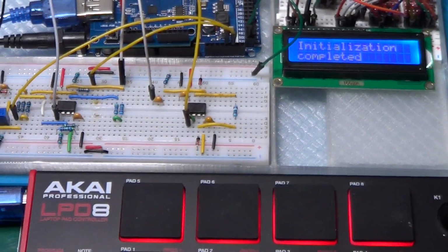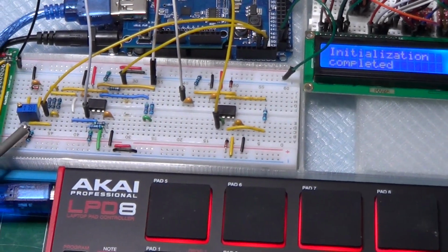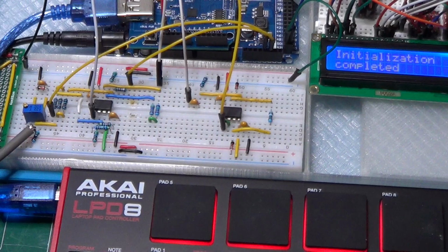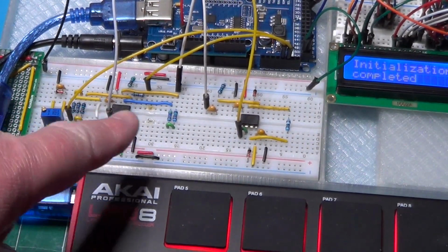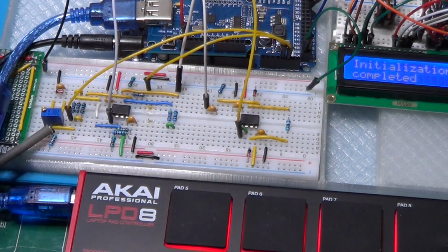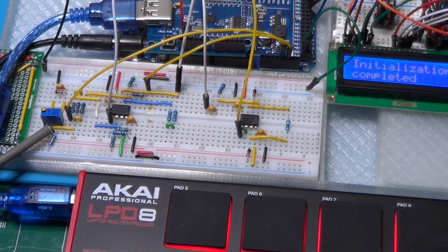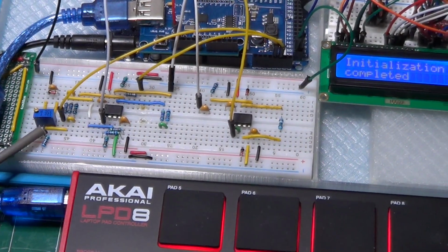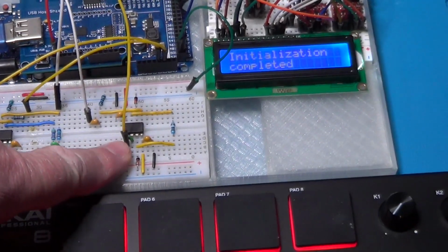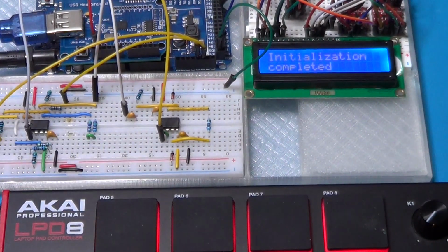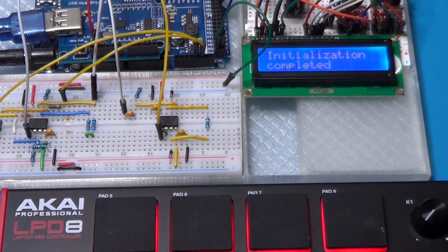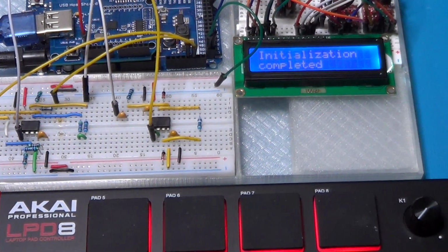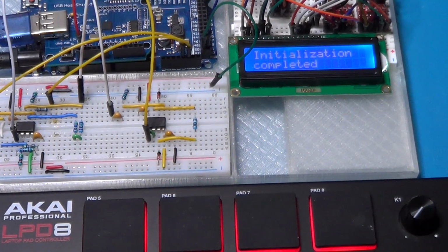This breadboard on the bottom of the platform holds the new circuits built for the new features. On the left side we have this dual op-amp LM358 that handles the generation of the CV signals for the notes and for the velocity. This other IC on the right is also an LM358, and this one is used to handle the trigger signal, and it uses the circuit we examined earlier, which I also previously used to generate trigger signals for other modules